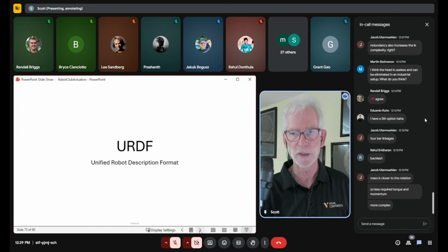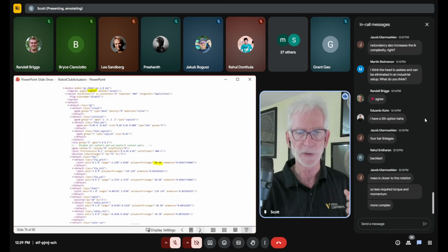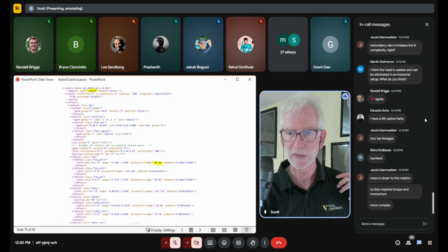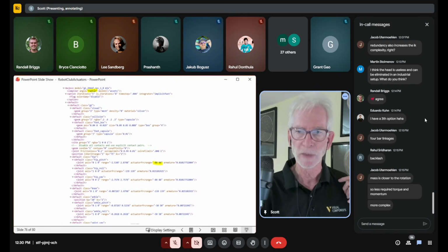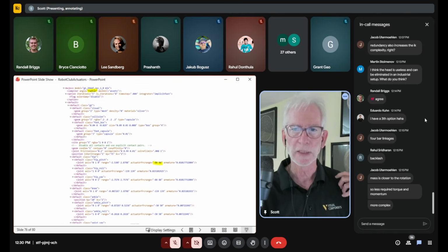So if you're not familiar with the URDF format, you need to do that. It's basically an XML sheet that allows you to bring in data that you can find in a GitHub out there, to get an idea of what the masses and payloads are of various bots, and the center of gravity to do the calculation. And what's neat is that in there, they actually show you the motor specs. Some of these things highlighted here in yellow show at a hip exactly what the torque is going to be there.